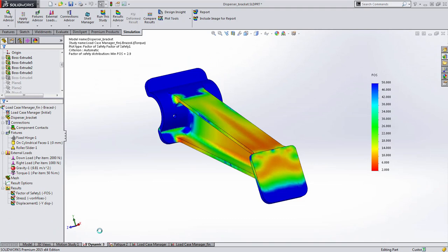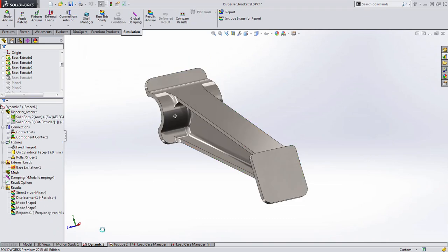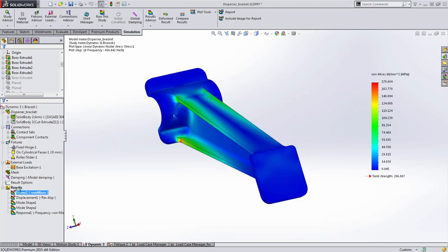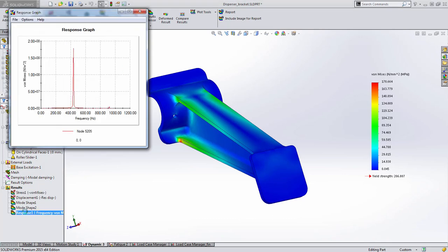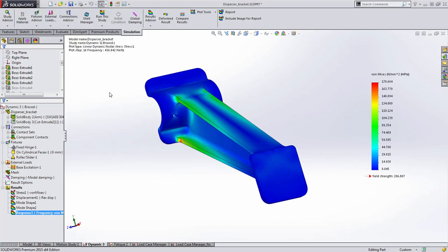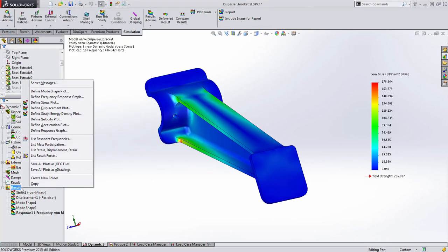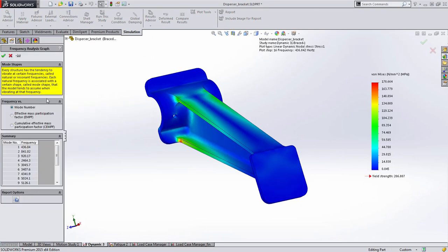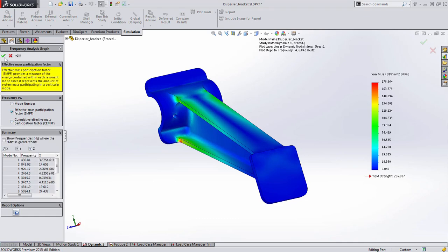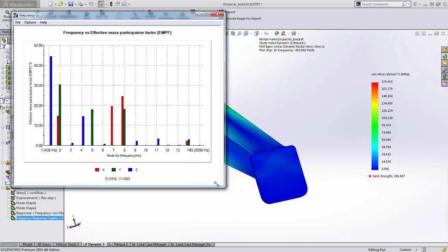When it comes to vibration analysis, durability and fatigue are a common concern, but it's also beneficial to identify key characteristics for the various vibration modes. This is in addition to the response frequency graphs we have, which don't give us the insight we need into the key contributions for our different components. So a new frequency response graph has been added to enable review of mass participation for the modes. This helps in identifying the direction being excited by a particular mode, as well as the proportion.